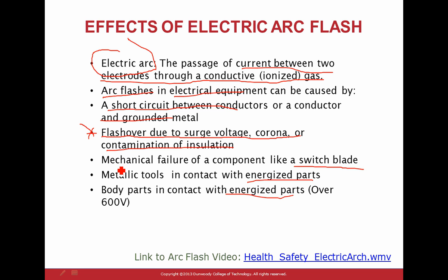But if you have a 2.8 panel, and power coming to it at the level of 2.8, 120, obviously if you have more amps, it will be bigger. And the worst of the worst is if you have 480. If you have 480, always think arc flash. With 480, don't open any panel without putting your gear on for 480.